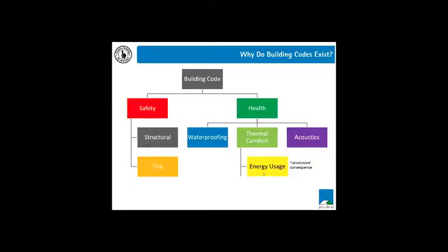When we start doing that and we do that well, we start to figure out that we have an unintended consequence of the unintended consequence, which is moisture. That moisture comes from the occupants' internal moisture or from external weatherproofing that leaks into our construction systems. Both those moisture issues make up part of the health discussion, as well as keeping the building thermally stable, thermally comfortable, so that we don't stress ourselves.